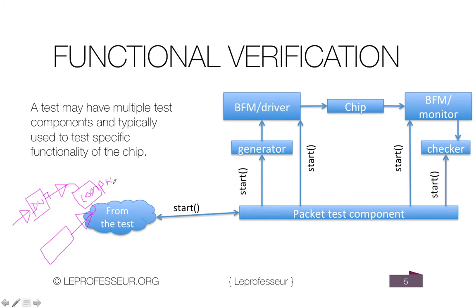And the output from your internal module, which you have written as a functional module. Okay. The same stimulus is going to both of them, and that will tell you whether this test passed or not. So that's a very simple idea, but here we are putting this very simple idea in a SystemVerilog test bench framework. Okay, so you got a very basic idea about functional verification.